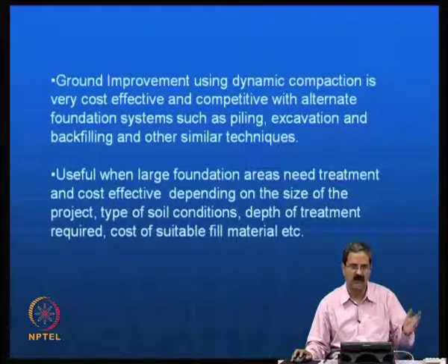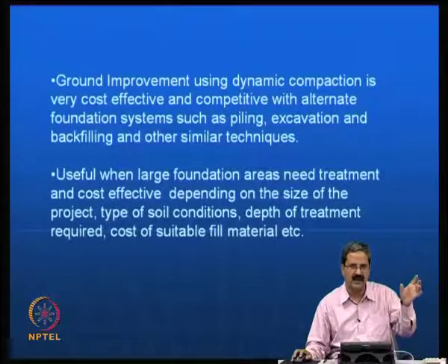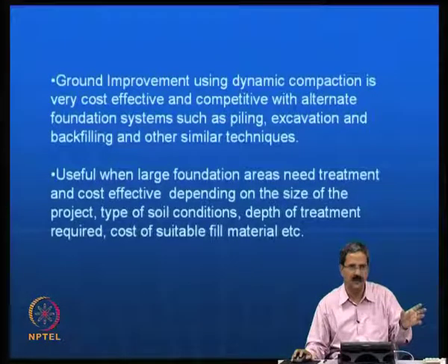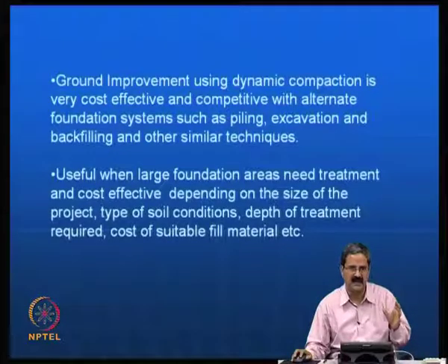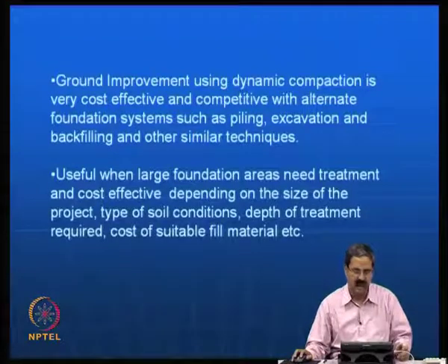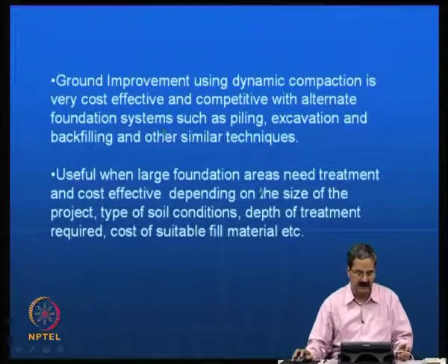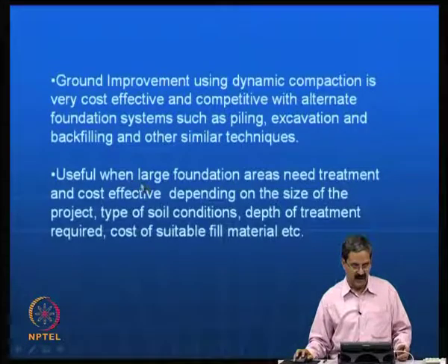Particularly when you design the pile foundation, you do not consider the soil between the pile groups, or what its role is. Maybe you can consider the skin friction in a sandy material, but its contribution is largely ignored. But in ground improvement techniques, we just compact the material to what we want. If you specify some performance, say for example SPT 20, you will get it. You have to do it till you get it. So, particularly this is very useful when you are trying to handle large foundation areas, say for example coastal areas.